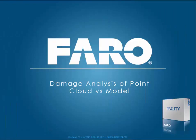Taking that one step further, we've exported the Polo data from FARO Scene as a PTS file. We then bring that into Reality and we overlay that data against a model within Reality of a similar vehicle, and then we simulate the level of damage, and whilst at the scene it was estimated that the vehicle was only doing 30 miles an hour. In the software we've proved that by doing the analysis work.